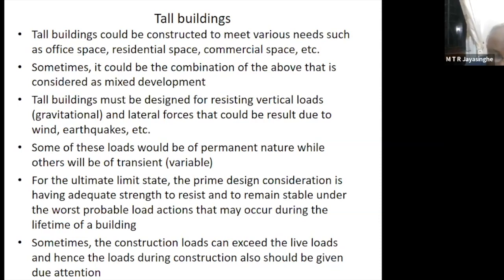In the span, I will consider the long span as not critical. So I will use the minimum reinforcement I can have, but in the short direction, it can fail. Because of that, in the shorter span direction, I will be a little generous. Everywhere else, I will try and minimize as much as possible.